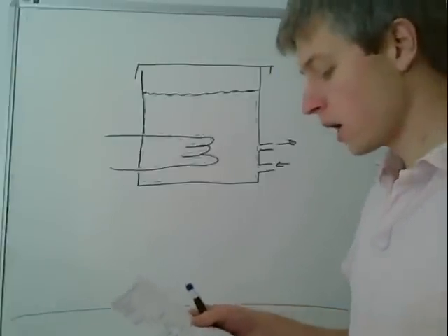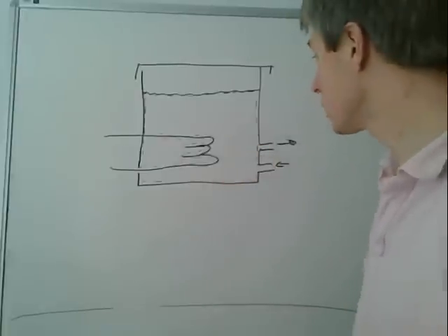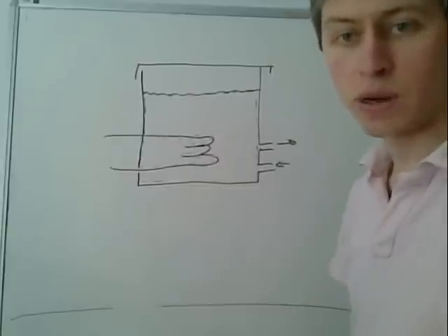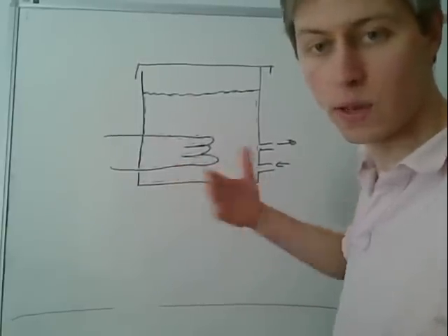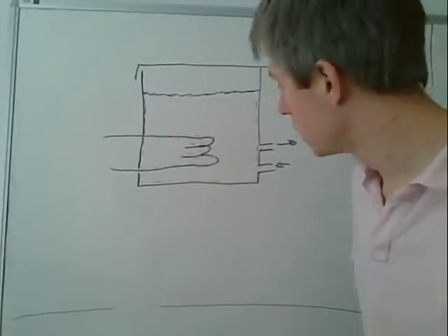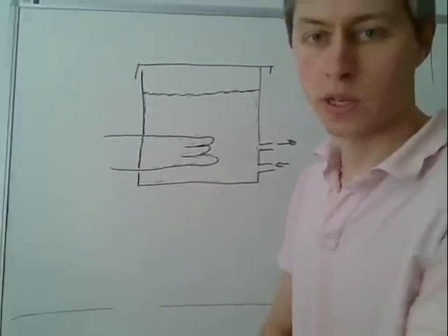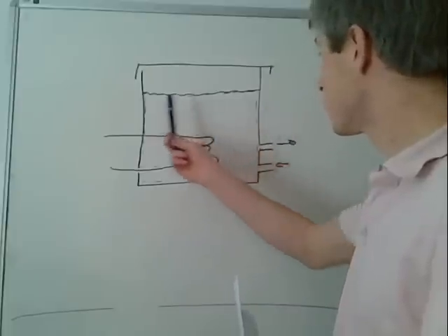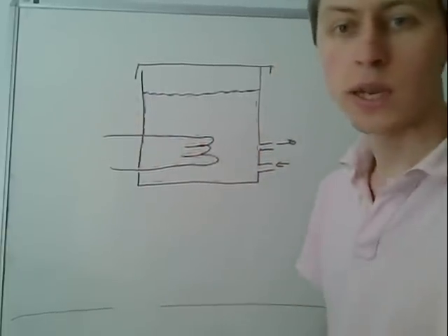Now, how is heat and work transferred in this system that we've now defined? Well, this heating element's receiving electrical power and being heated by electrical resistance, so it's going to be hotter than the water potentially. Heat will be conducted from the surface of the heating element into the water, and then can be transferred through the liquid by convection and further conduction. What else? We can have heat losses to the walls of the tank.